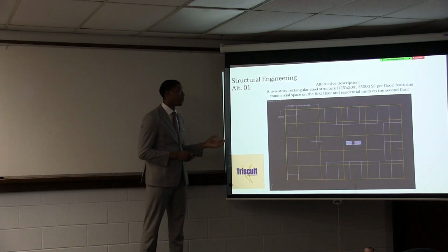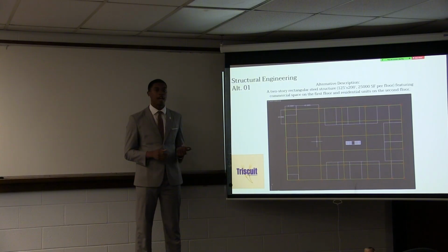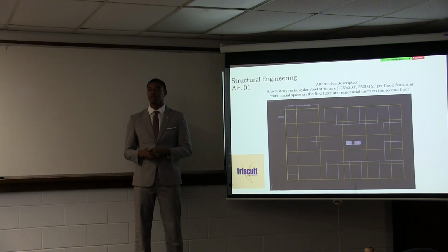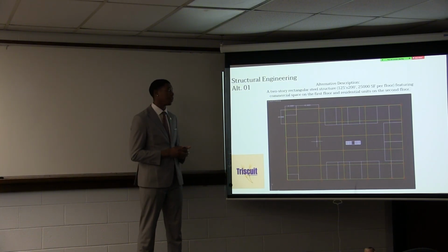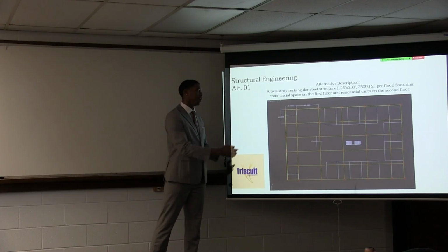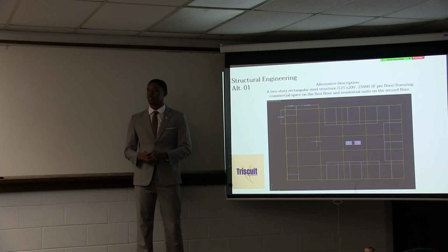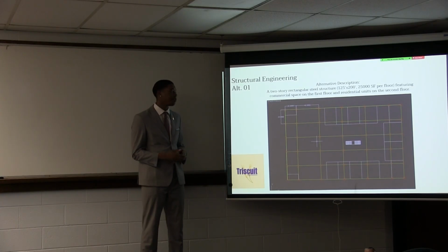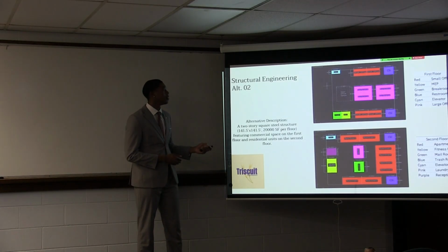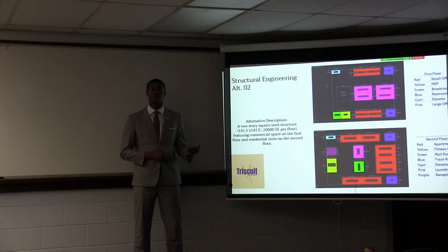And here we have our column design, where we imagine our column spacing would be. From the AISC, it is typical for your column spacing to be anywhere between 20 and 40 feet. So we decided for those first 2 sets of columns to be 20 feet apart, and then 40 feet, and then at that last end, back to 20 feet again. But moving up and down, we have those spaced out to be 25 feet, still consistent with that 20 to 40 feet recommendation.